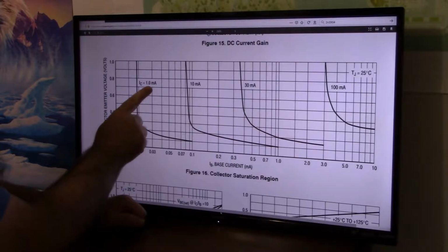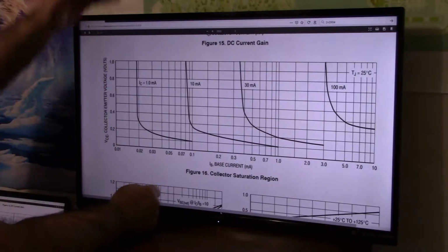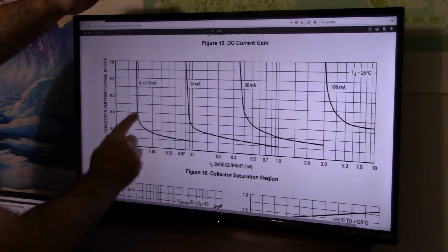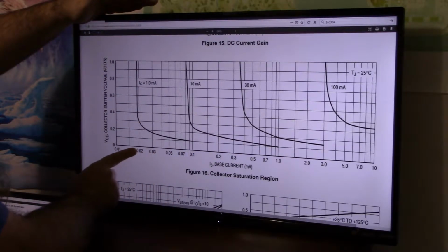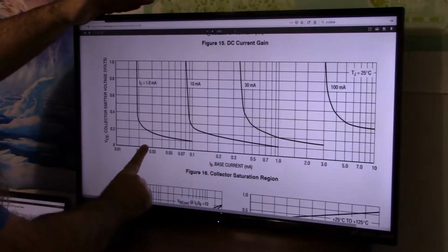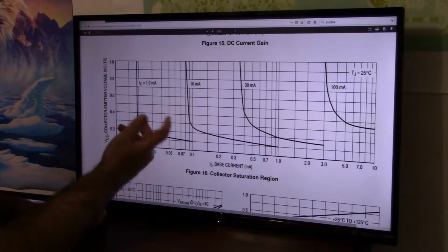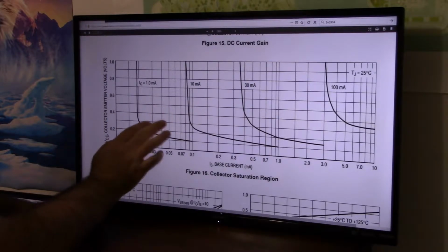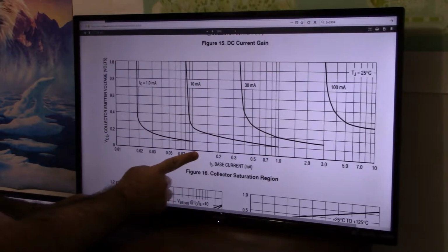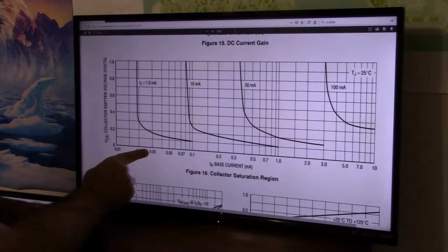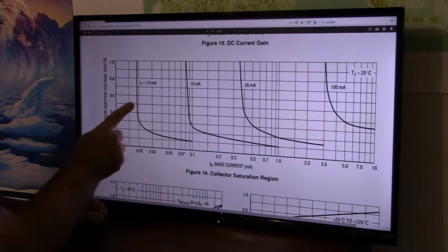Because if you need 1 milliamp and you're supplying voltage that's way up here, this line is going to be up there. So anywhere along this point, you can turn it down and down and down to about here. Let's say that's safe, because transistors vary. Warmer, colder, slightly different construction, there can be a little wiggle. But it tells you that you can turn your base current way down, and at a certain point, it'll just stop, and the current is not going to change.